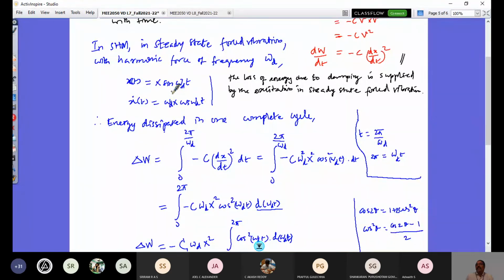So any structure which is damped, and I give an excitation, that means giving some initial disturbance, it is going to oscillate freely and die out. That is the nature of damped free vibration. But I want to make that structure vibrate forever with a decided frequency of my interest. Then what will I do? I will excite that structure. Instead of disturbing it, I will apply a sinusoidal wave, that is x sine omega t.